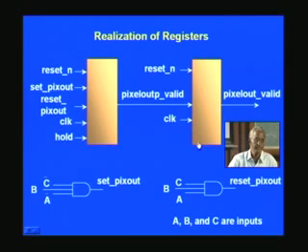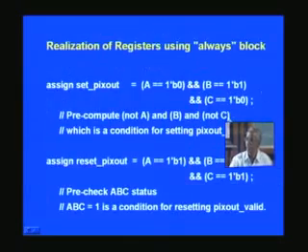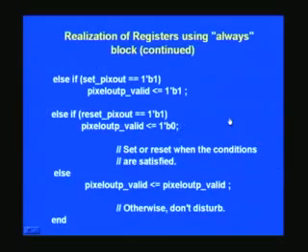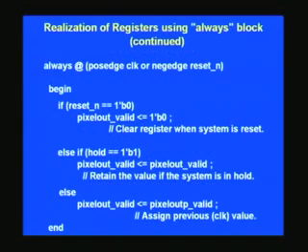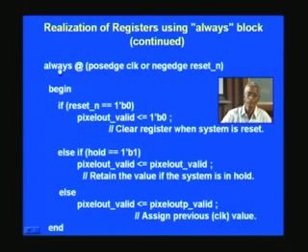This is only to delay the signal, as we had mentioned earlier, so as to keep pace with another signal such as data, actual data itself, say pixel out, which is the data. And we will now see this flip-flop implementation, which is very much similar to this. So once again, we use always at positive edge of clock or negative edge of reset, and you notice that when you go through the course, you will get again and again the very same structure all through, and that is the beauty of this structure.